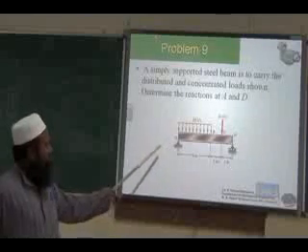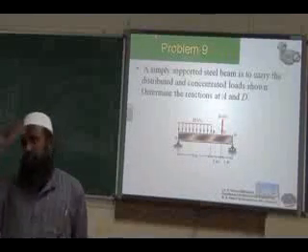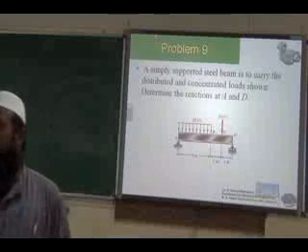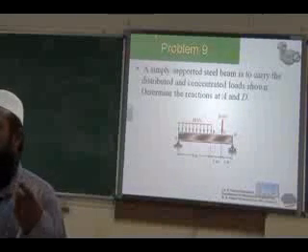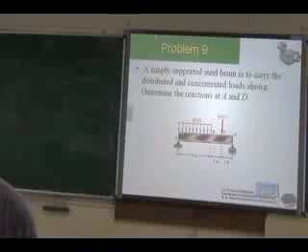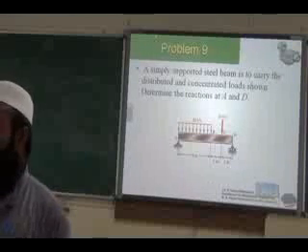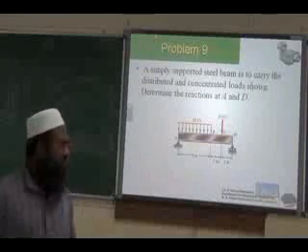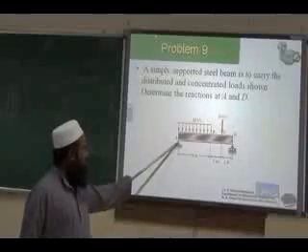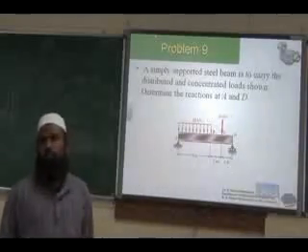Here both are simply supported beams. Okay, this beam we call simply supported. It just supports, and it is not allowing your beam to move in y direction only. Move along the y axis. No movement is allowed in y direction at point A as well as point D.